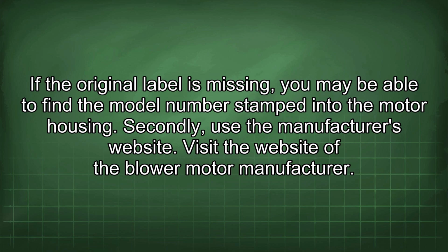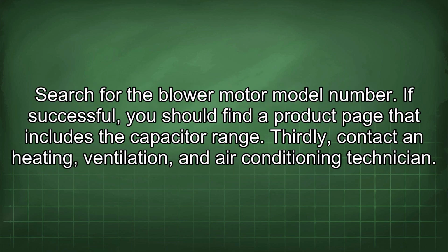Secondly, use the manufacturer's website. Visit the website of the blower motor manufacturer. Search for the blower motor model number. If successful, you should find a product page that includes the capacitor range.